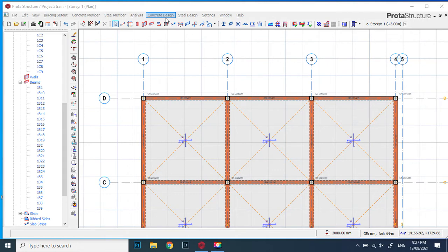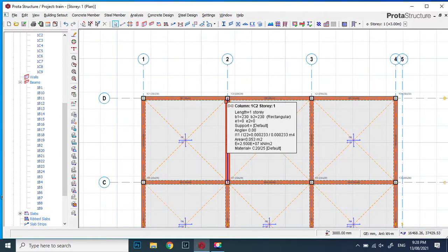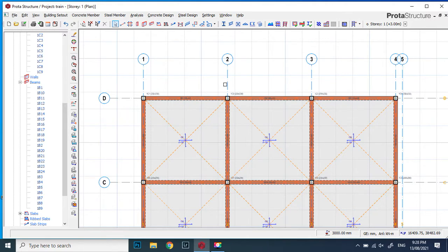So the first we'll do, if it's possible, please pay attention to the end. There are some things that I will be saying that if you don't listen to the end, you will not understand this. Very, very important. If you can create a cantilever beam, do it. But if not, then just create cantilever slab. If you create a cantilever beam, it's firmer and stronger than if you just use only a cantilever slab to carry everything. So we'll dive straight right in.